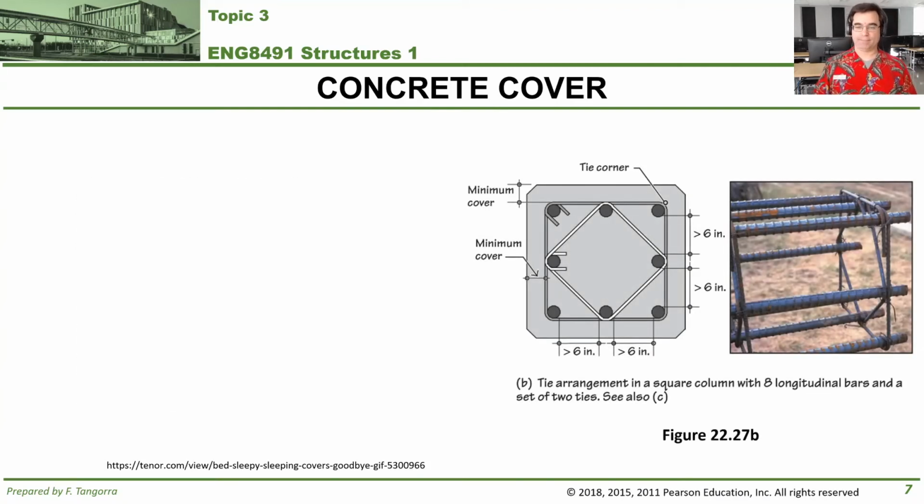So here's the thing. Concrete cover is the amount of concrete that you put on top of the outermost layer of reinforcing steel, like right here. The idea is this. Reinforced concrete is often exposed to the elements: rain, snow, wind, pooled water, maybe salt from ice prevention techniques.